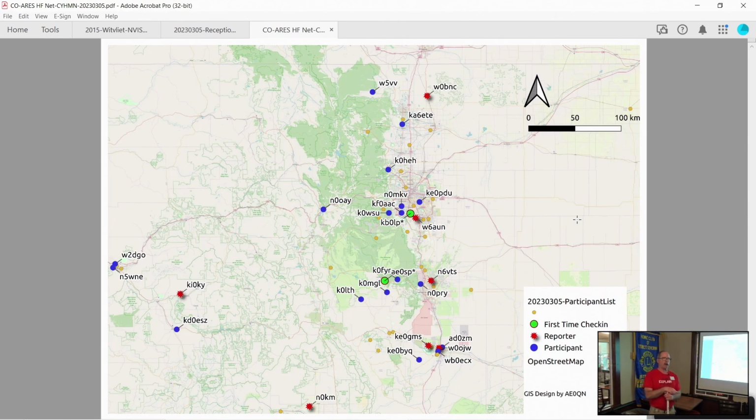On the random wires, you need to stay away from half wavelengths and multiples of half wavelengths because the impedance shoots up through the roof. So you don't want to be near a half wavelength. You don't want to be near a quarter wavelength if you're using a 9-to-1 balun because it's not a good match anymore. That's why 72 feet's good, and it's more than a quarter wavelength even on 80 meters. So that's where that number comes from.